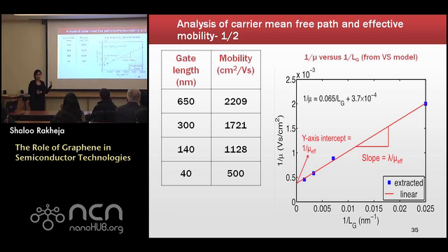All of them are included to extract these mobilities. Contacts, sometimes they give us the values and sometimes they don't. And it's again a question of how many parameters are you optimizing, what are you optimizing, are you getting the right results and things like that. So you think they use a two-terminal source-drain measurement and try to take away the contact effects? Yeah, but for these I didn't get any data from IBM on the mobility of the devices. So these are actually extracted from the virtual source model.